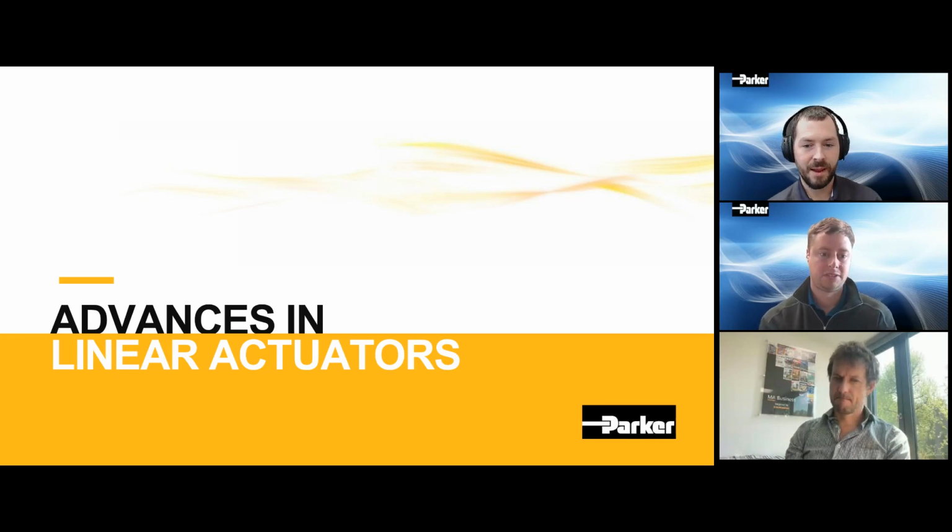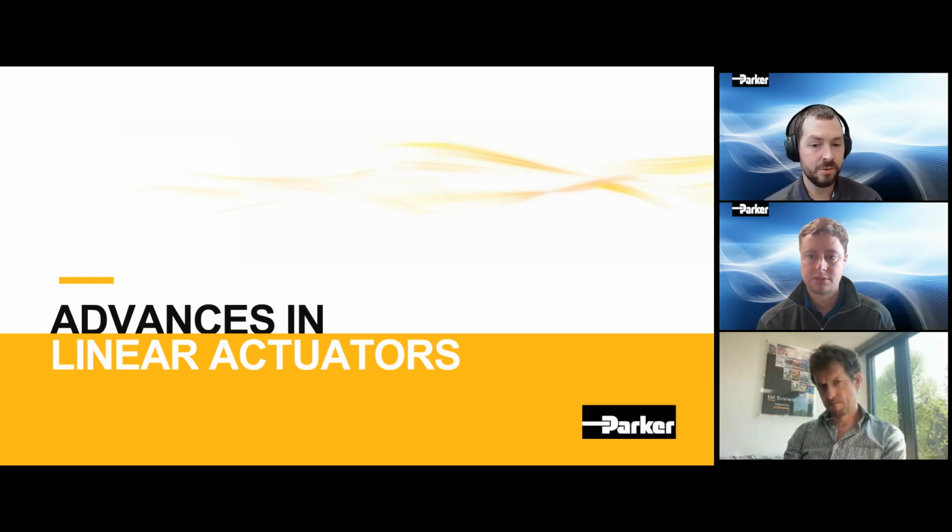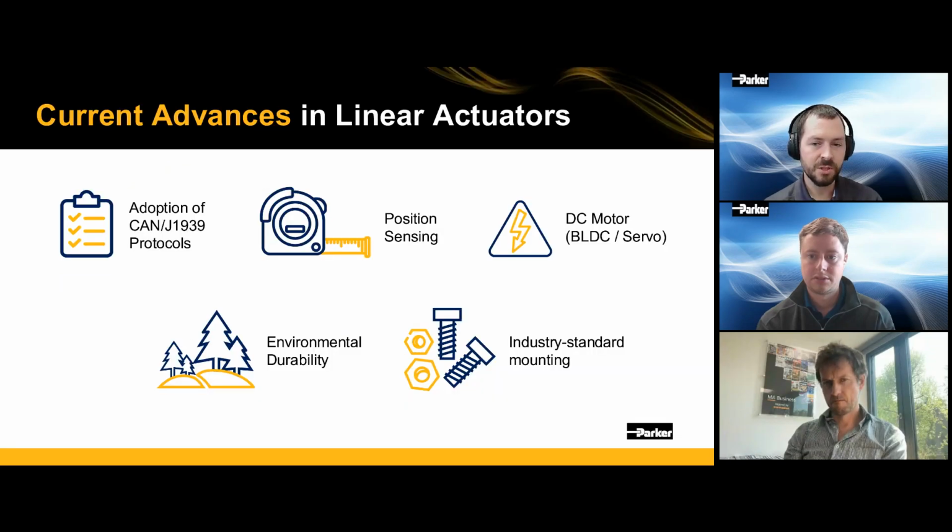However, I don't want to pour too much cold water on the linear actuator space for mobile equipment. There have been a lot of advances lately that make them attractive for those auxiliary functions and those medium duty cycles. So where have we seen the advances recently in the linear actuator space? So first is the communication. CAN bus is a big thing, and we're seeing more and more linear actuators adopt J1939 or CANopen. It really allows precise control, wiring simplification, and also really good data monitoring.